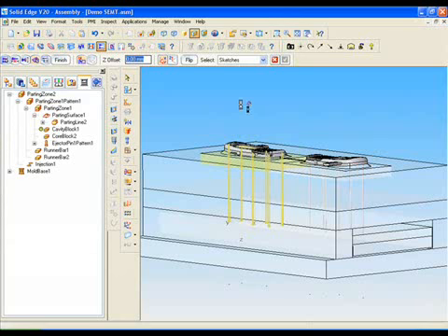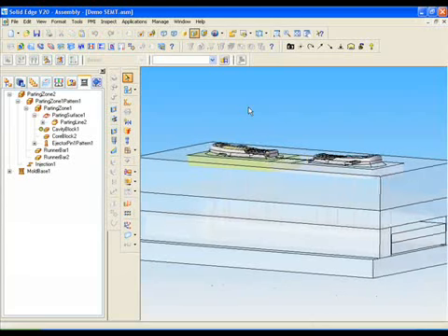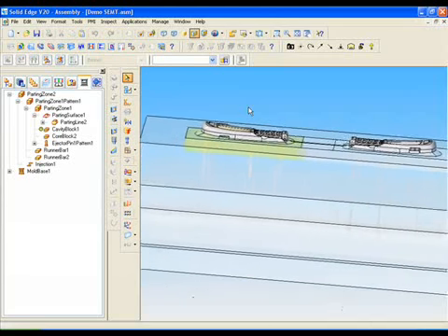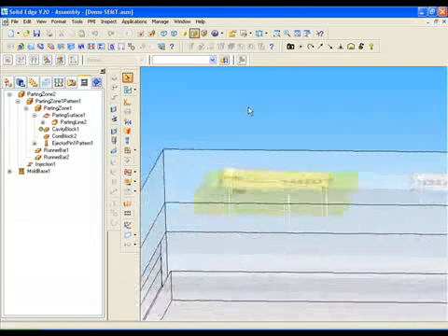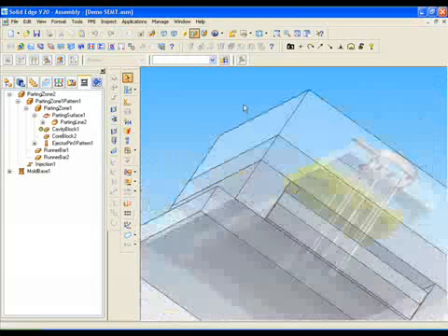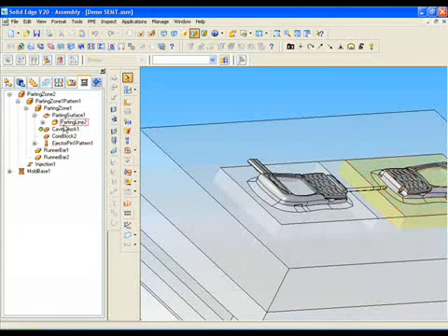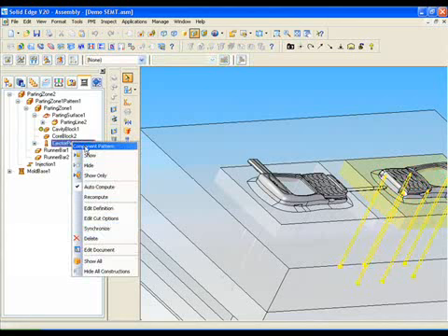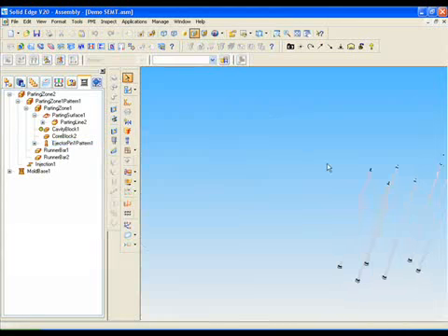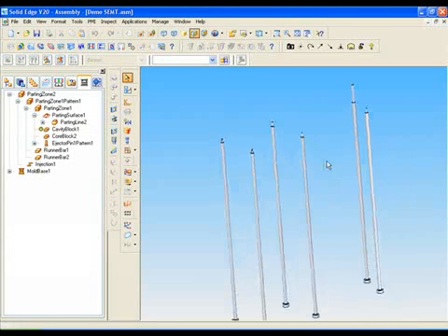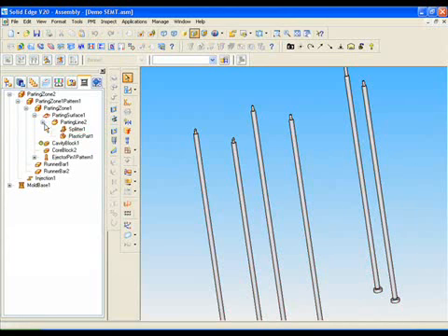While it updates the remaining features, let me just add that all sorts of components can be created using sketches to define the positions, and a single sketch can be used to create different patterns of components. Check that the ejector pin pattern entry was added in the mold tooling edge bar below the parting zone, indicating the dependencies. Also check that the ejector pins were trimmed by the parting surface.